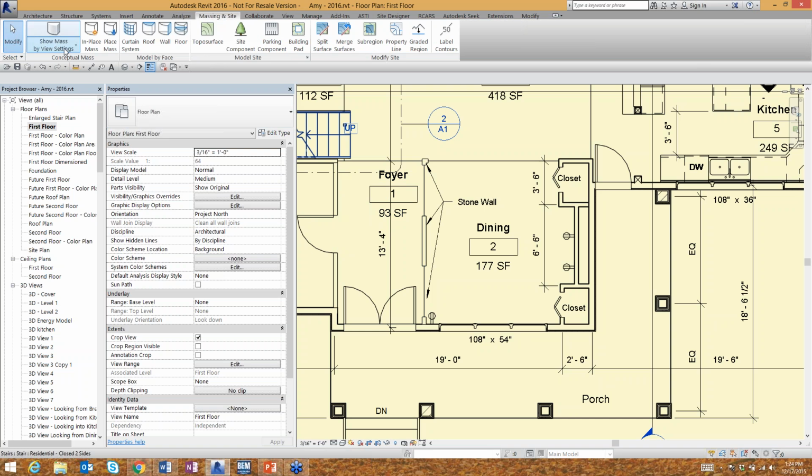Yeah, there's a whole side to Revit that's for conceptual tools in there, as far as just doing some conceptual masses. I can create some conceptual families in there using a conceptual modeler that's very, very similar to SketchUp. Basically you create a shape based off of an outline, and once it creates the shape, it's got push and pull pins in there that you can push and pull to modify the shape. So it's very, very similar to that SketchUp push and pull feel.